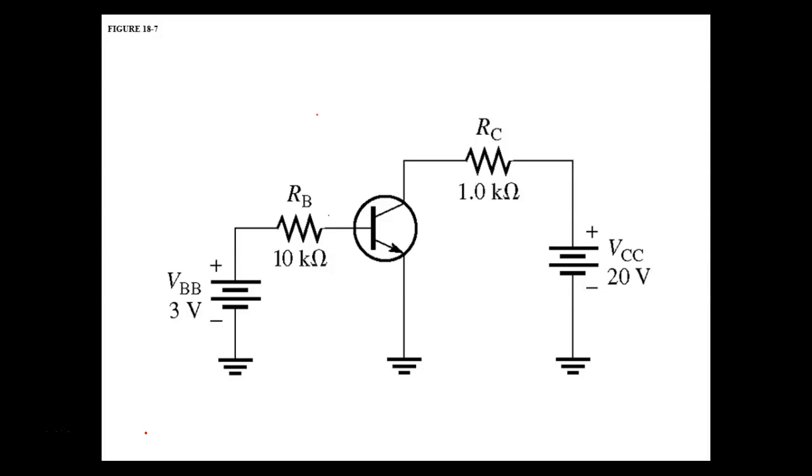So what do we do? We drop this down to 2 volts. Y'all calculate this for me. So what we want to do is get the voltage, collector to emitter. Yeah, but here we're going to use 2 volts instead of 3. Same thing, right? So let's go ahead and calculate it. And we use that to calculate IB, and we're going to keep the beta at what? 100.